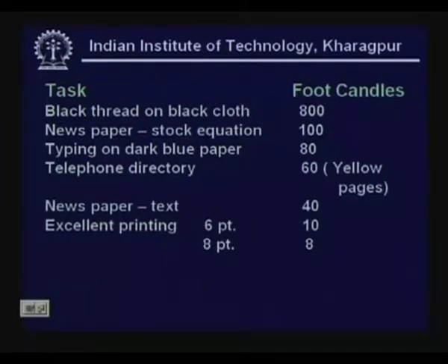The newspaper text, the white background with reasonably big text, about 40 foot candles. If the printing is good, well shaped letters, you find for a 6 point you need about 10 foot candles, and you go to 8 point you get 8 foot candles.